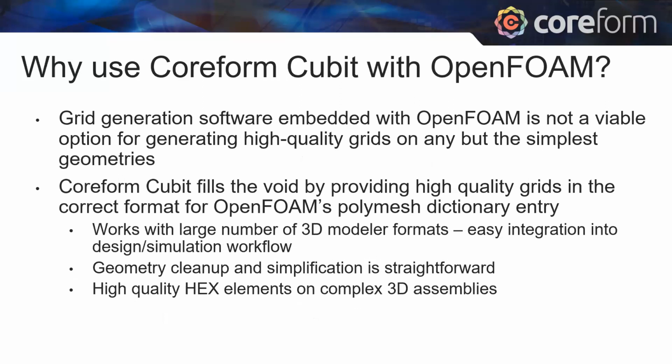It has some simple grid generation software embedded with it, but if you do anything that's any larger than, say, an axisymmetric nozzle problem or a tank, anything more complicated than a simple geometry, what they have built in is not a viable option for generating the high quality grids that you'll need for solving your problem. Coreform Cubit fills the void by generating high quality grids in the correct format for OpenFoam's polymesh dictionary entry.